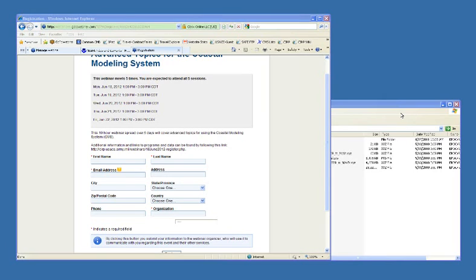The only question then might be whether it's relative to NAD 27 rather than NAD 83. Those two datums are just a little bit off, one is a little bit skewed from the other. It's really tricky if you are not given any kind of information about where to get that data from, or how to know where you are in space.